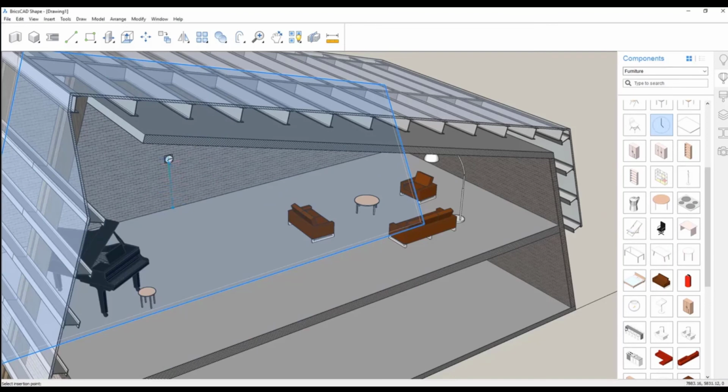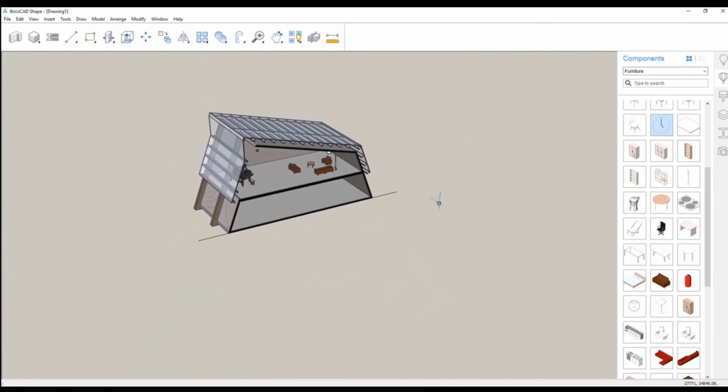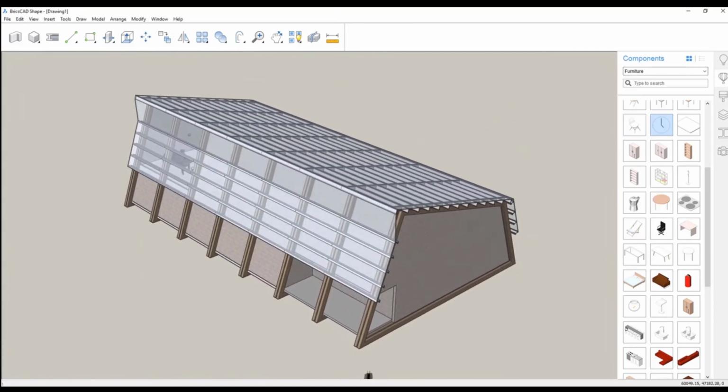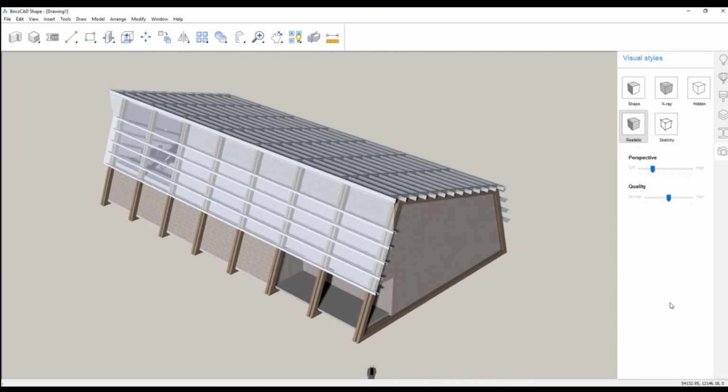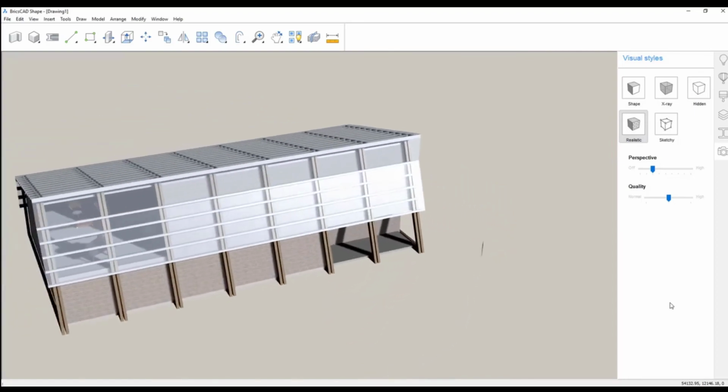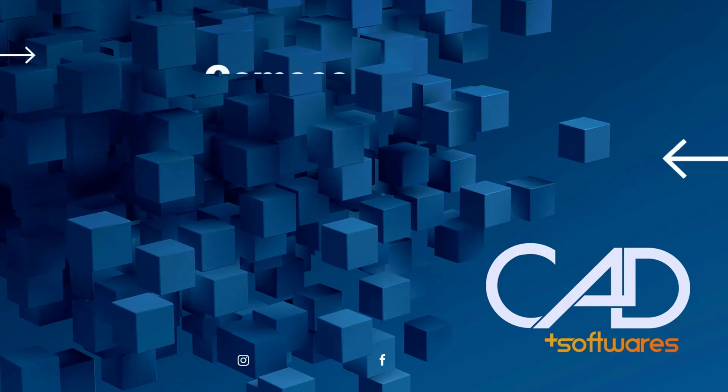It loads into BIM with the open command. And then very quickly, tools like Bimify and BIM Connect will allow you to very quickly create a finished building information model from which you can extract construction drawings.